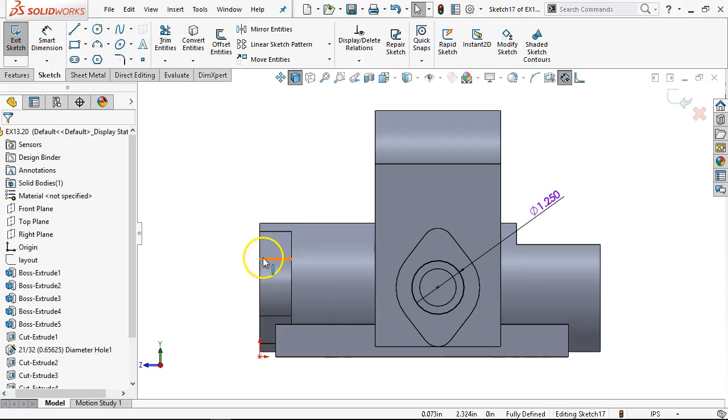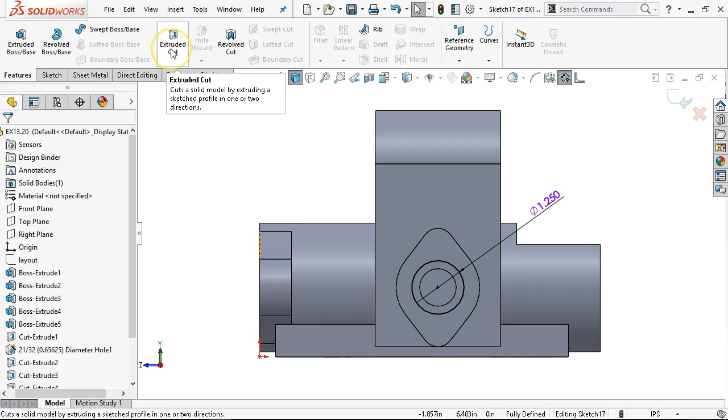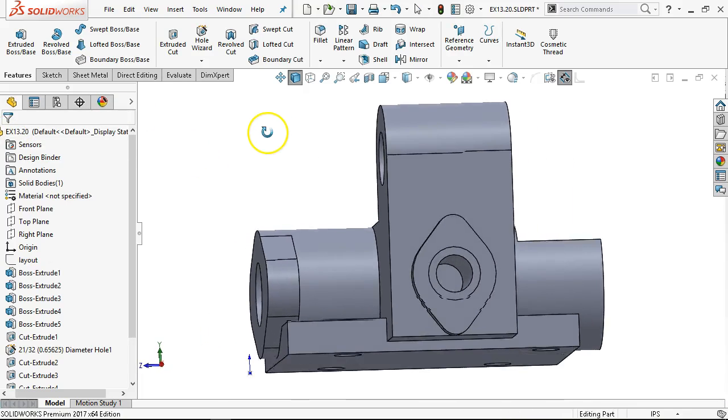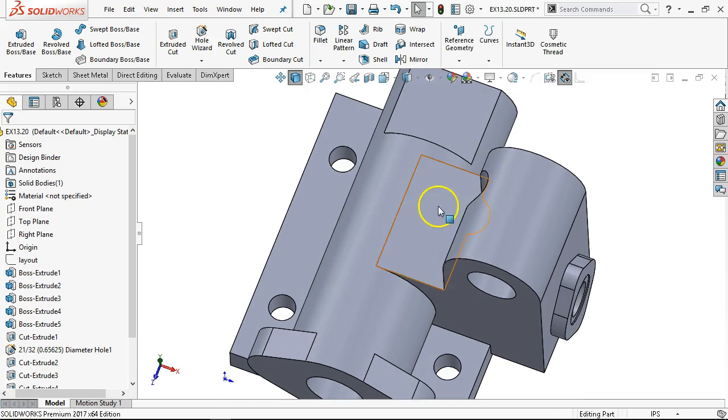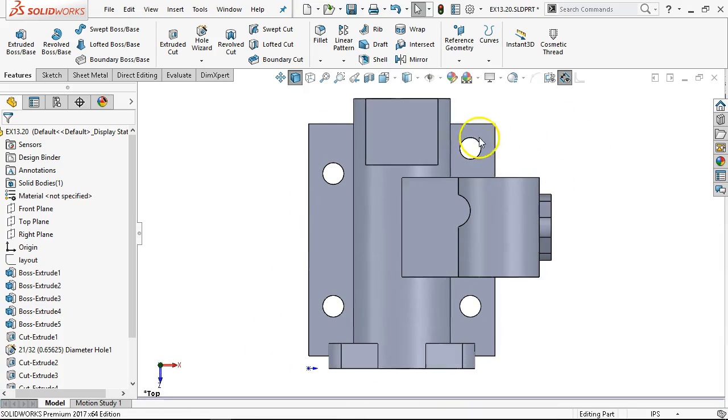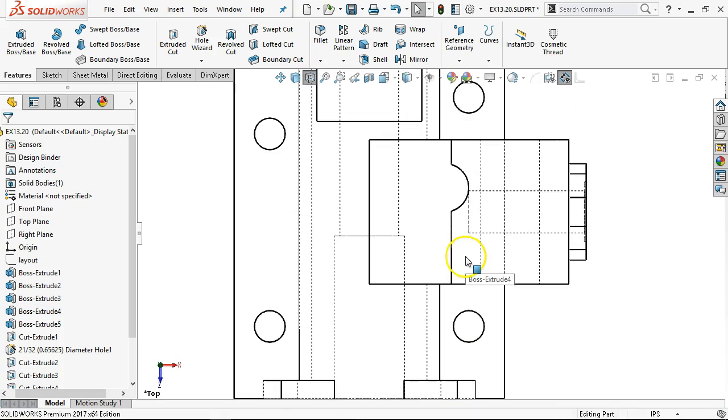Alright, so we made that 2.5 deep. Spot face is usually 30 thousandths to 1/8 of an inch, so 0.030 to 0.125. Well, we're past the point of getting usable data out of this particular drawing, so making another design decision, let's go to our tapped hole and we'll jump into the center.